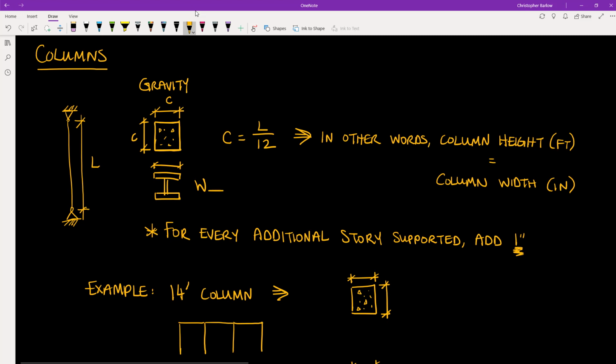And note that with steel columns, we select a dimension based on the unsupported length. And so that gives us typically either a W8 or a W10 or maybe a W12 depending on how tall the column is. But we didn't really talk much about the overall height of the building. And that's because with steel sections, when we add more stories, we typically just add more weight to the section, this number here. And that analysis is a little more complex. And it won't really have too much of an effect on the architecture.